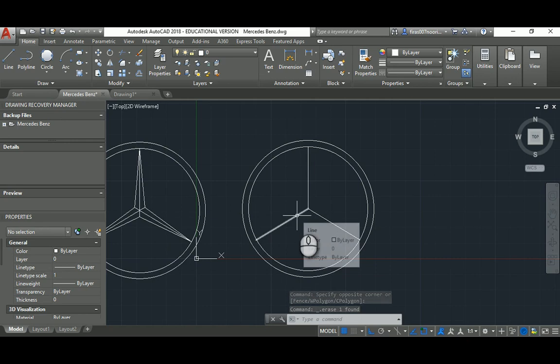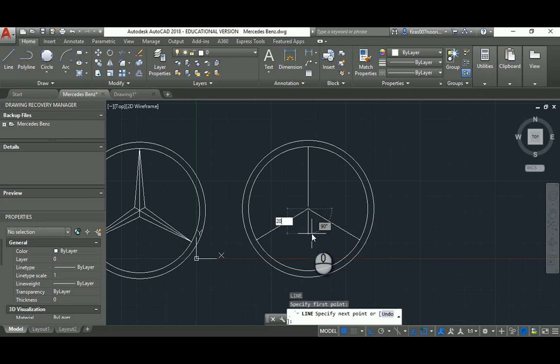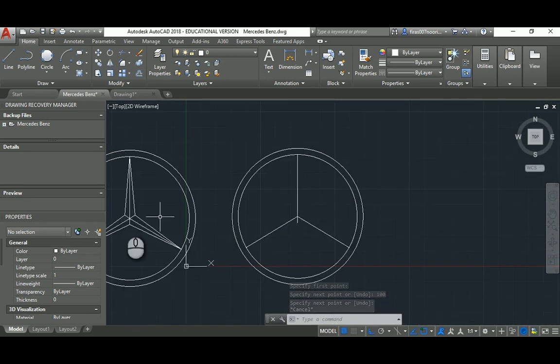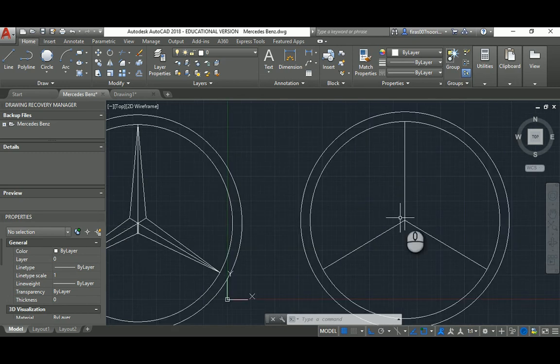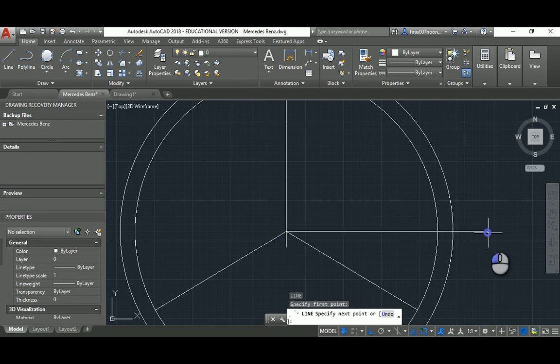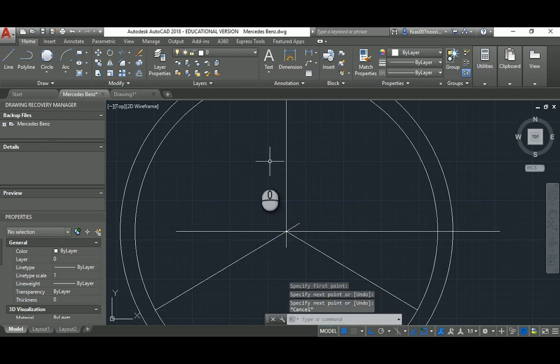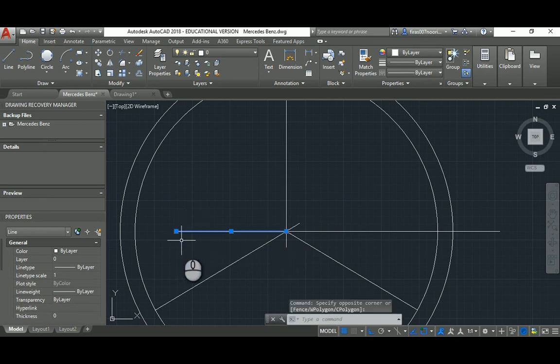Now the other angle is here, and you go like 200 mil, or let's say 100 mil down, and then you need to identify this point and this point. Same thing here, three lines. So again, that's a 90 and you needed 120, so it should be 30. So let's say relative, it's 100 with an angle of 30. Same thing here, from the beginning to the end is 180. You should subtract 30, because from here to here is 90 and another 30 makes exactly 120. So from this point to this point, we have to take 180 and subtract 30 out of it. So it will technically be 150.